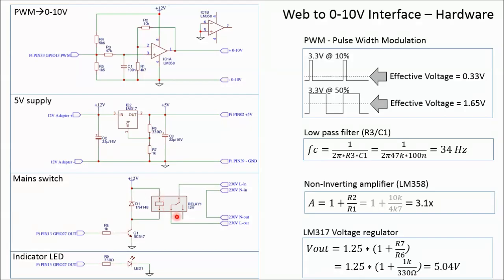Note that I use the break contact of the relay. This is to ensure that the light is on during boot up. As mentioned before, it takes 1 to 2 minutes for the Node-RED program to start after mains is switched on. The inversion, anyway, is easy to fix in the software. GPIO 0 means on and GPIO 1 means off.